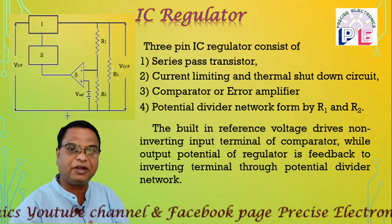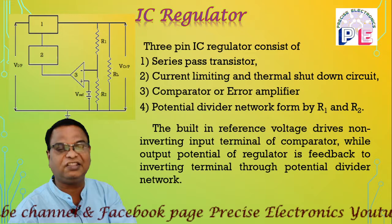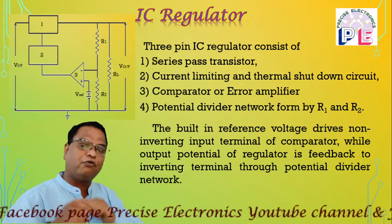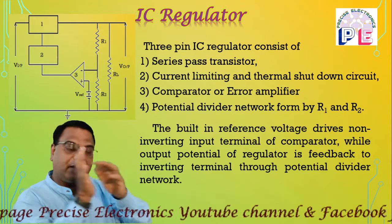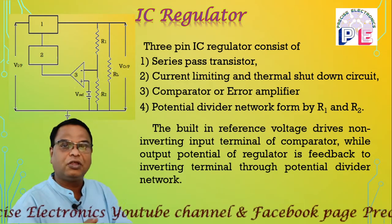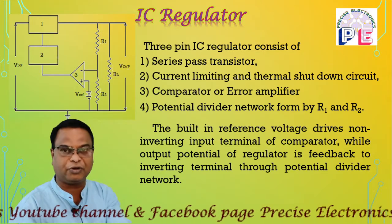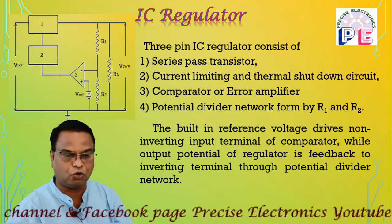In case of a comparator, the input signal is compared with some reference. In this case, the inbuilt reference potential is connected to the non-inverting terminal, while the output voltage of the power supply is fed back, and that feedback potential is connected to the inverting terminal through a potential divider network formed by two fixed value resistors R1 and R2.